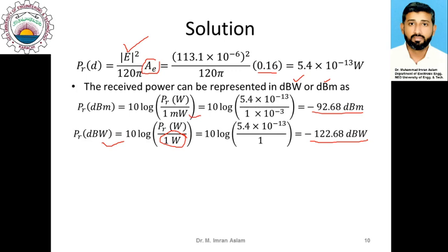So we conclude our discussion here, summarizing important points related to the two-ray ground reflection model. Let me mention that the first important thing is that the calculation is based on assuming two different rays: first one which is coming directly in a line of sight, and second one which comes from the ground reflection. The important thing to note in the two-ray model is that the received power is dependent on the fourth power of the distance.